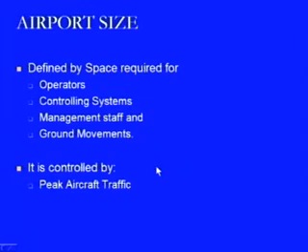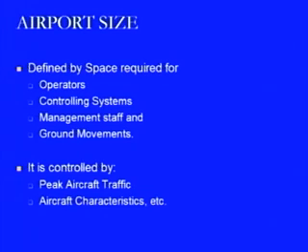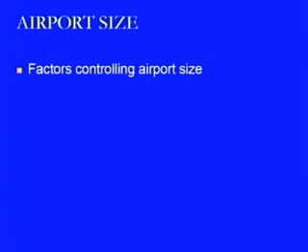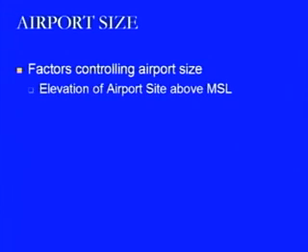Therefore, it can be controlled by certain things like the peak aircraft traffic. During the peak time period, the overall traffic of the aircraft will govern what the size of the airport should be. Then there are the characteristics of the aircraft that we have seen already. So, we will be looking at these things one by one, that is, the various factors which control the airport size, like the elevation of the airport site above the MSL.